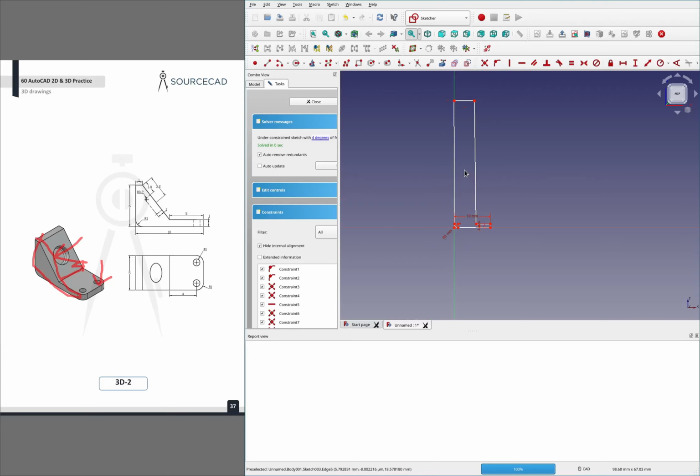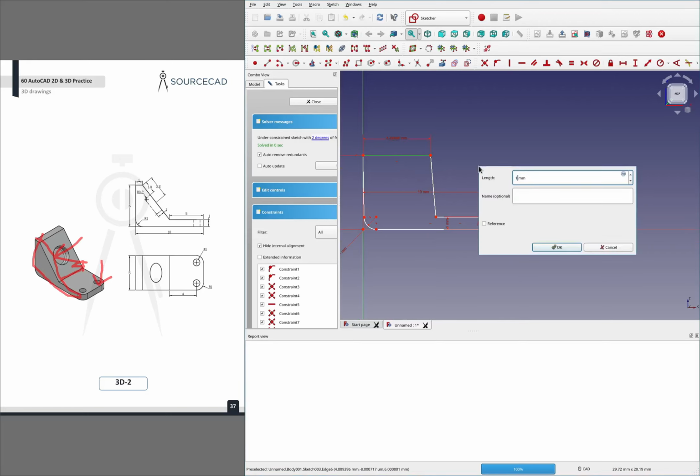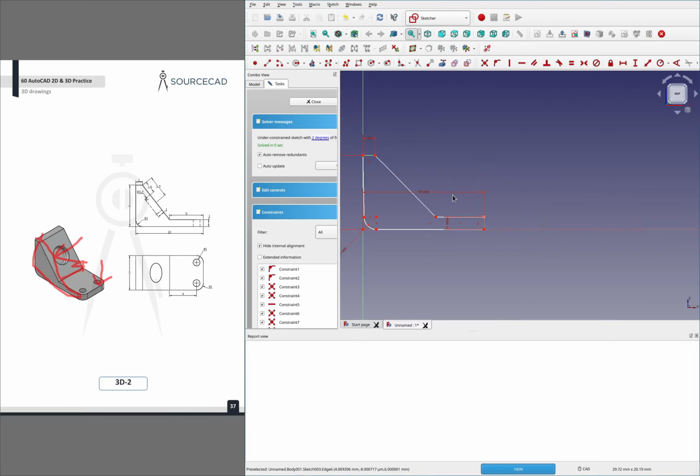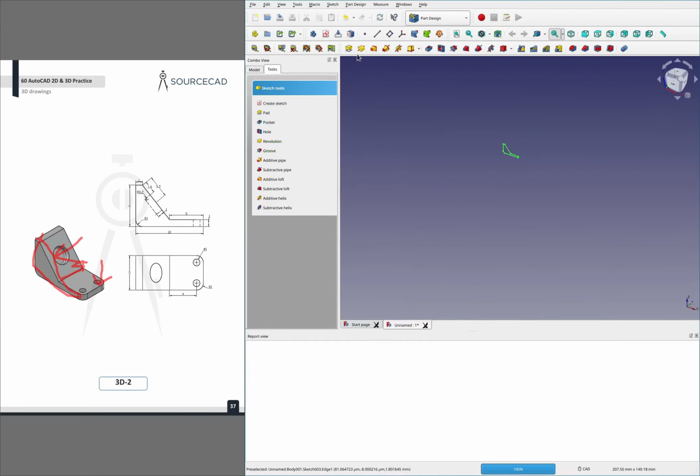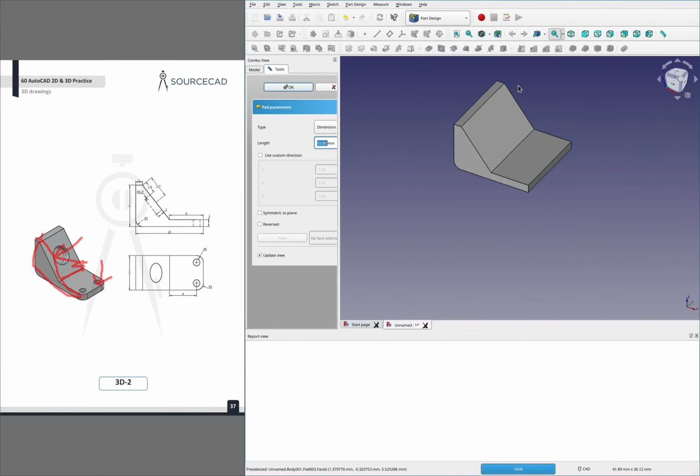And then this one here, 6 units tall. Starting to take shape. Horizontal, 1 unit. And then this one, horizontal, 5 units. Let's see, you need to be vertical, and we are fully constrained. Go ahead and pad this, pull it off the drawing there. It's a 5.